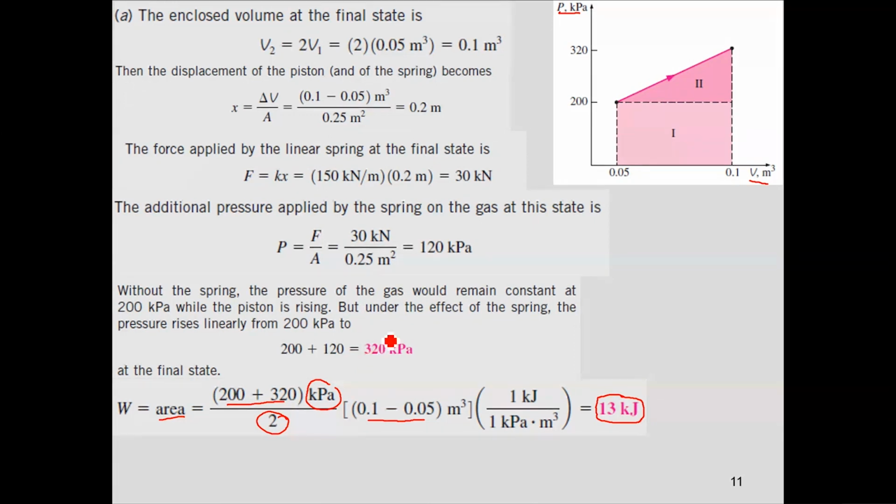Yes, sir. All right. Now, how would you find out the area or the work done by the piston against the spring, or the spring work done? 1/2 kx square, 1 by 2 kx square. In this you have to be very careful, in which you have to use x1 and x2, because you know that this distance has moved from some x value to another x value.